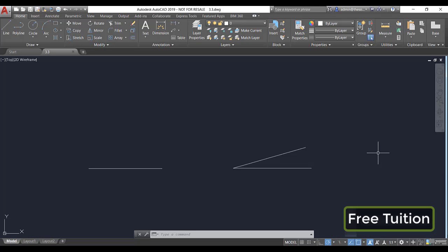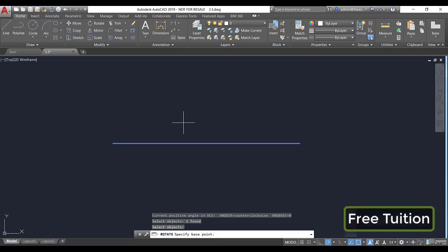So now let's talk about the rotate command. So the rotate command is on modify panel, and right here we have this rotate tool. So select this, and now we need to select the object which we want to rotate. In this case, I'll start with a line on our left. So I'm going to click on this line and I'll press enter. Now AutoCAD will prompt you to specify base point.